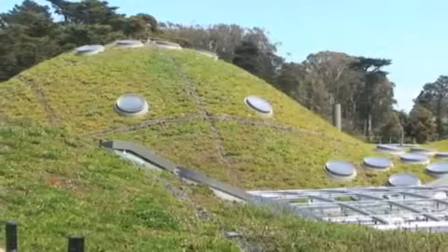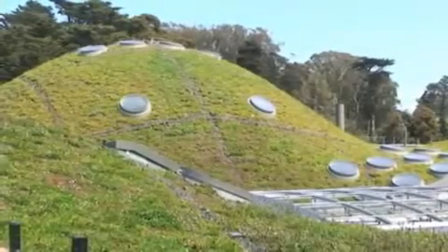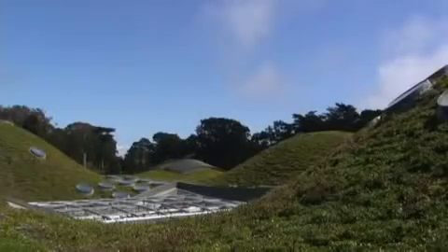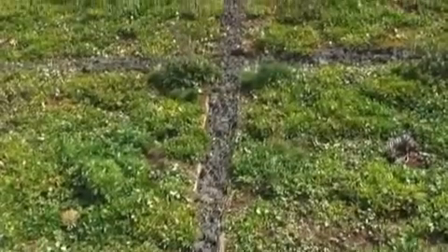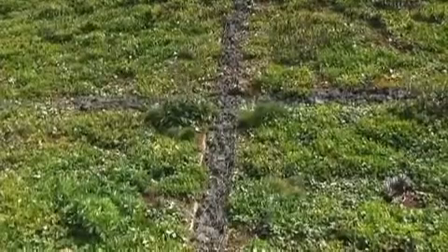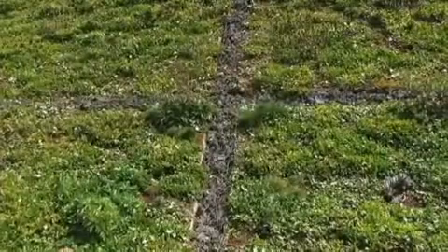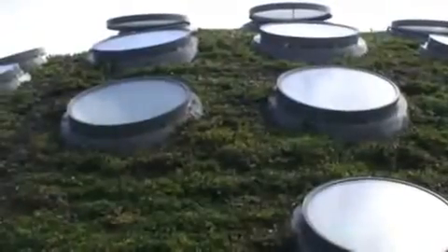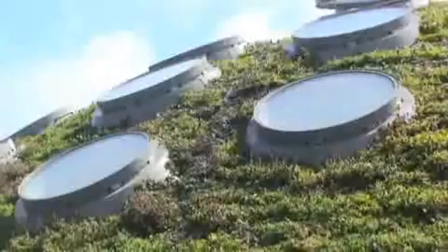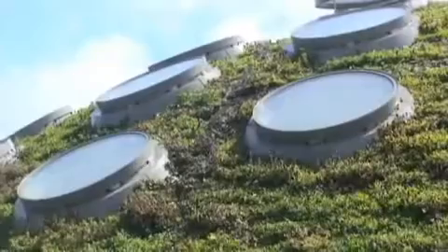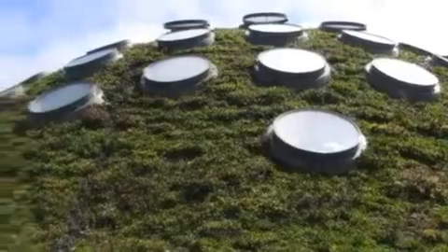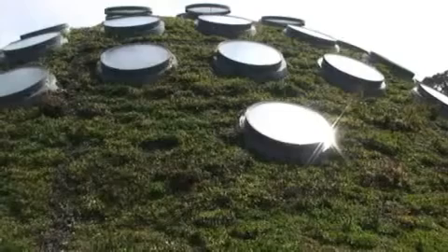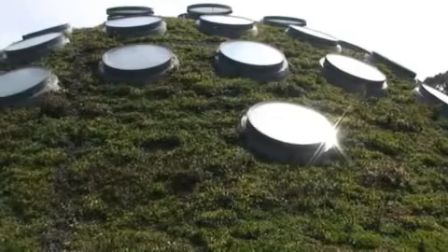And what we're seeing here is actually the grow out of the vegetated roof, which was 2.5 acres, which was grown off-site. So we developed a system of biotrays, which are composed of coco and bamboo fibers, and those are filled with highly engineered soil and 4 different plant species. And those were grown in Carmel Valley and then brought onto site and then assembled and tiled over the roof, almost in assembly line fashion.